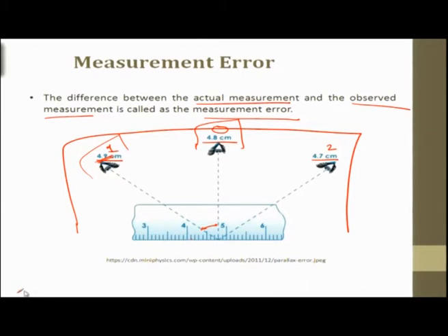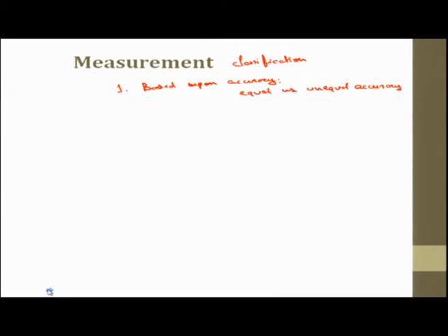Sometimes, at different conditions, the measurement values have different accuracies. So the methods used for reduction of measurements of equal accuracy and of unequal accuracy are slightly different. Thus, prior to reducing a series of measurements, a check needs to be performed to determine whether or not the measurements are of equal accuracy. This is generally done using the F test or goodness of fit test, the chi-square test, that we might discuss.